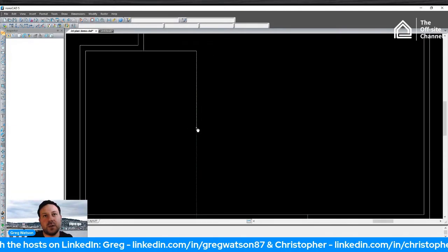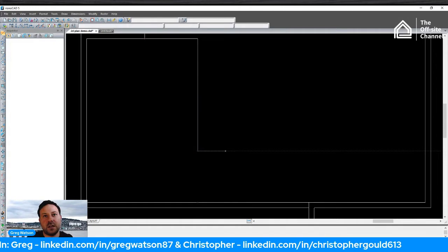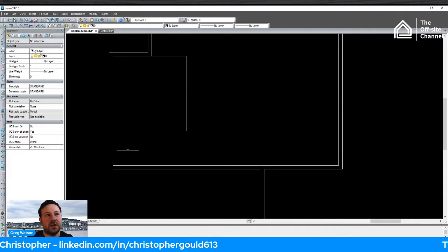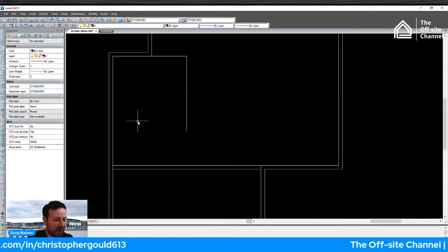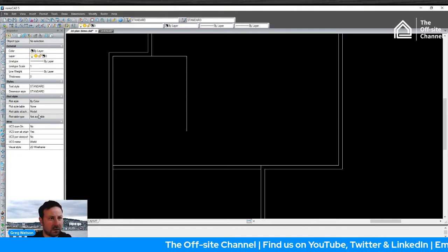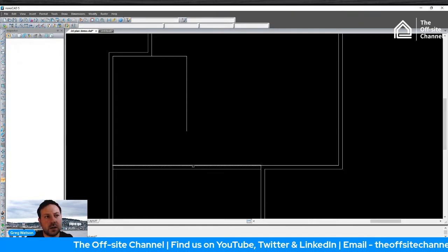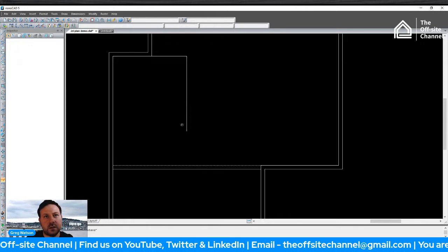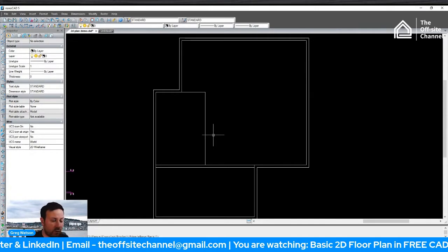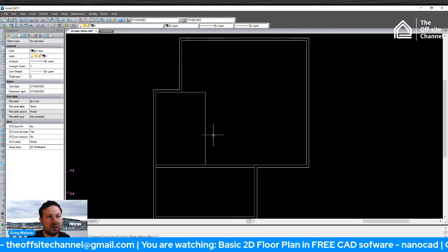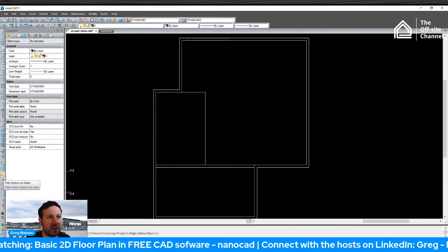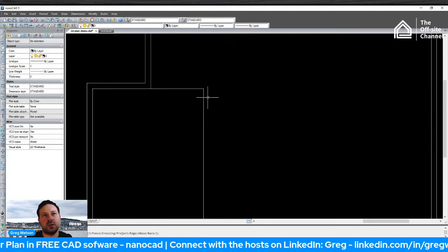Actually, what we'll do is I'll come down and I will extend. What I'll do is I will extend that down. So again, you can just type extend. Is there. Enter, and we're going to want to do that against that. Extend. Same for the trim tool. You would type trim in there. Again, that is on the tool palette on the left. Those two there. So those are the tools.